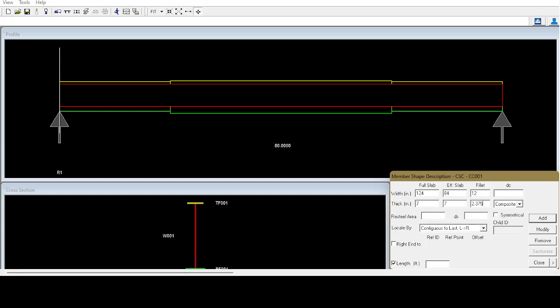As you can see, we have two different plate thicknesses on the top flange, so we need to calculate two different haunch thicknesses. If you have more information on your bridge and the plans, you can refine these calculations, but right now that's all the information that we have. So this will be just for the first 20 feet of our bridge.